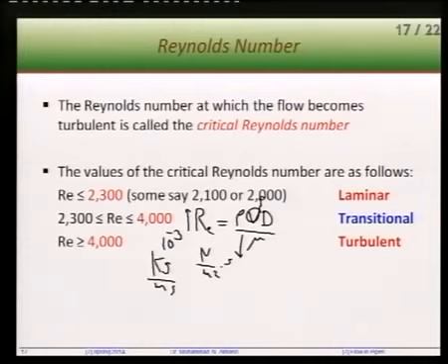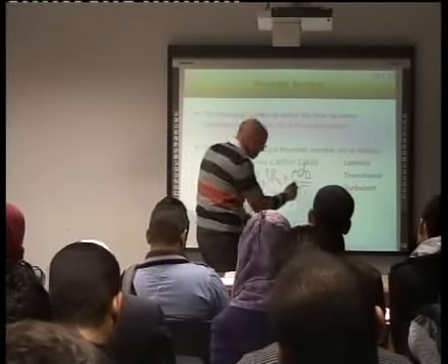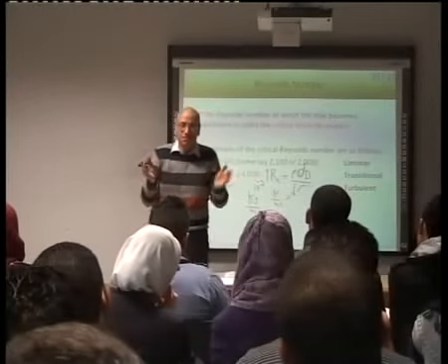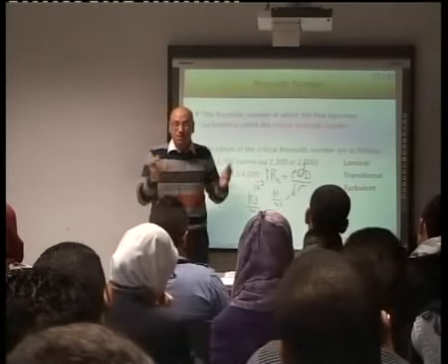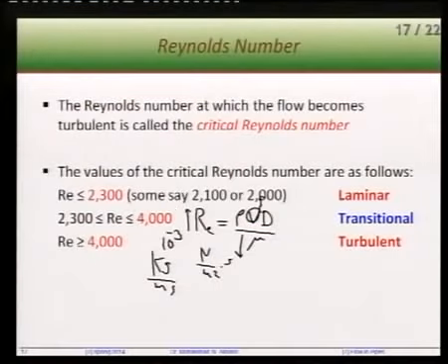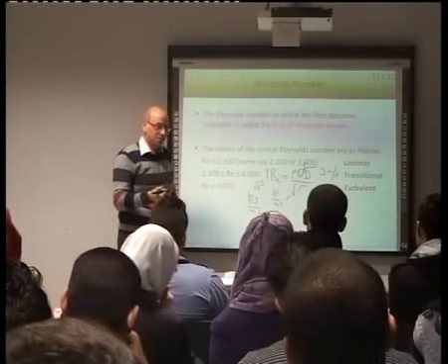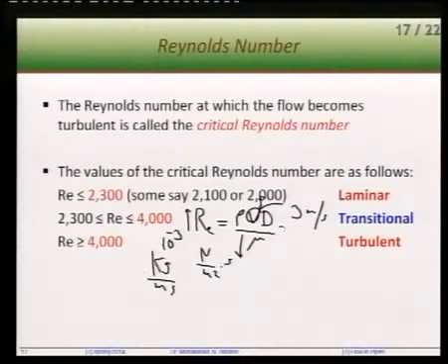Now, back to my question. In reality, now this is 10 to minus 3. The velocity, what would be a reasonable velocity in reality for water in a pipe? 1 meter per second. Okay, the maximum value could be, one is for design purposes, but it might go up to 3 meter per second. For the diameter, what would be reasonable? 1 inch is less than the lowest. It should not really fall below 2 inches.